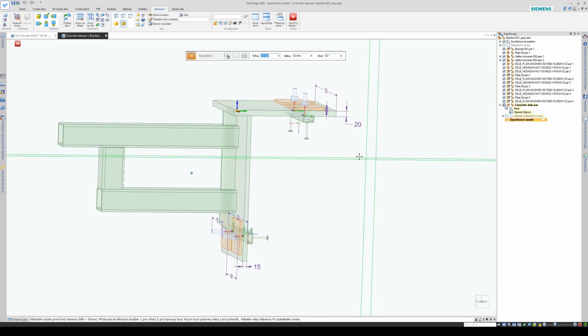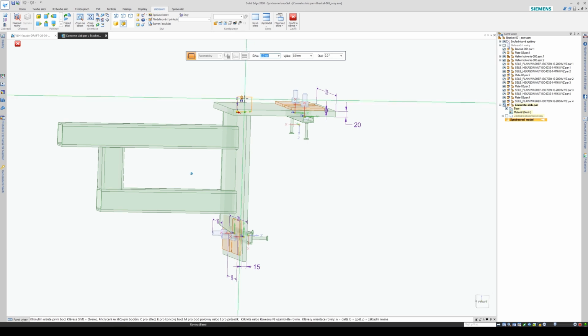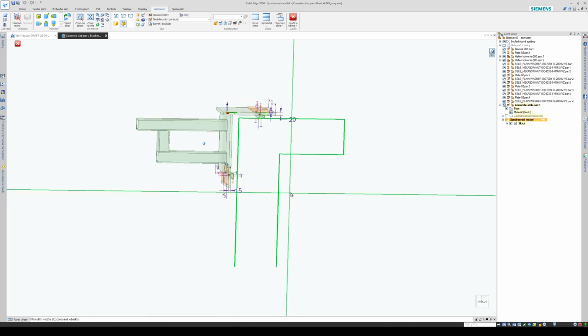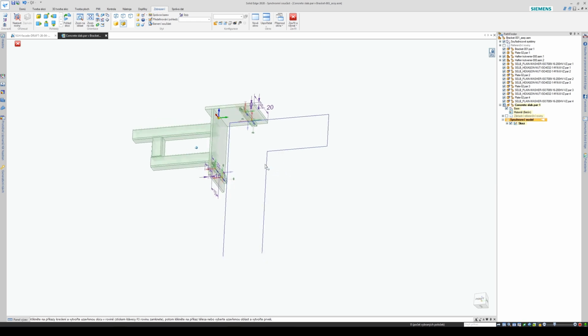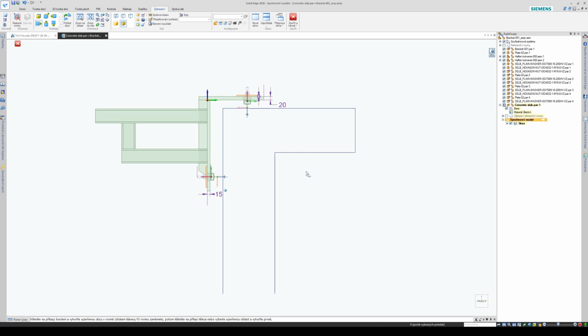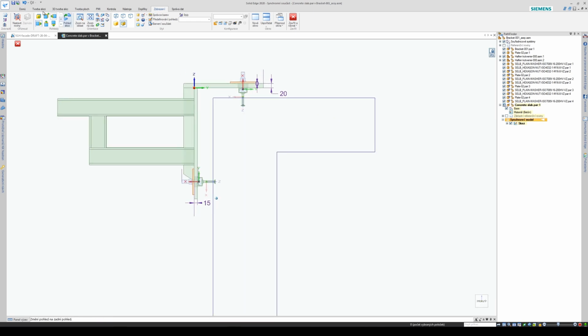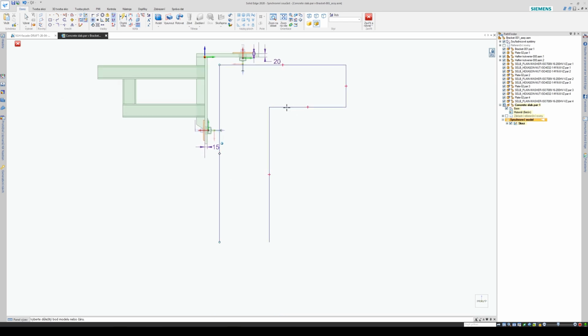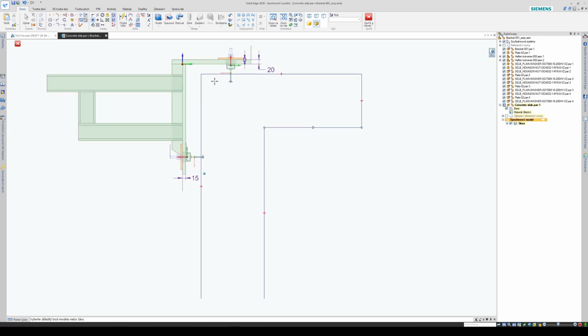In this case, I can just paste it in the synchronous environment because it was not a block, just the geometry lines. And in this case, I always try to make these lines, these copied lines from other drawings, vertical or horizontal, if they should be vertical or horizontal.